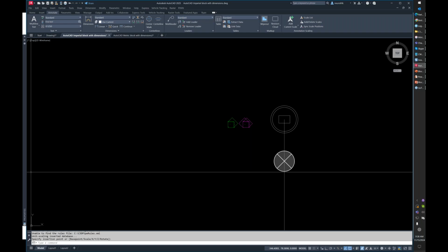But for MicroStation, this should work fairly well. Just be wary if you're using annotative blocks or dynamic blocks, that when you bring that stuff into MicroStation, there can be some unintended consequences, but for the most part, it works fairly well. Good question, Brian.